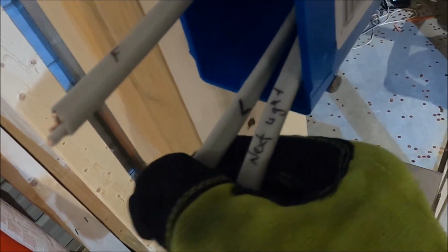So you definitely want to make sure you label the wires once you start getting a bunch of wires in a box. If this is the end of a run, or if I'm only putting 2 wires in a box, I'll usually just not worry about it, because I know which one I pulled for what purpose. But in this one, since I have 3 wires, I labeled them.